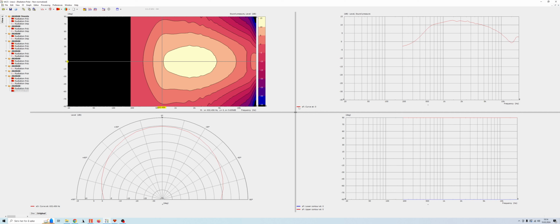Here we can see the frequency response of the driver approximately directly in front. Now, the levels are not right, so here we have to look at the relative levels. Now, as expected for this kind of waveguide, we can see that it's drooping off towards the high frequencies and also the low frequencies. I would not use this below, say, 600-700 hertz. Below that, it gives very little help to whatever driver is mounted in it. But above that, it gives a healthy bit of output boost.